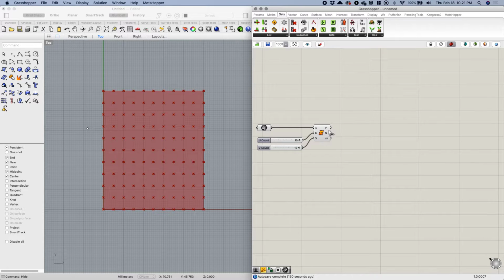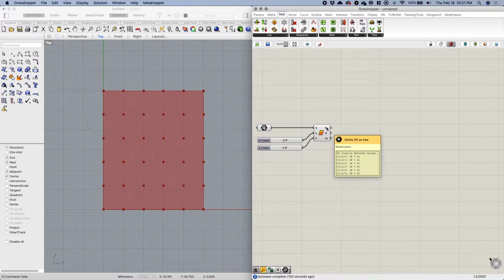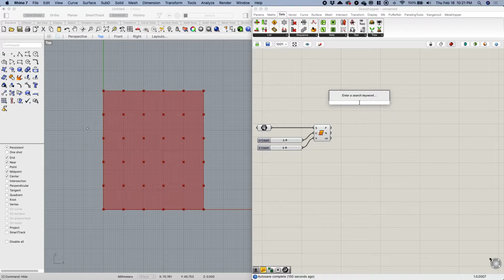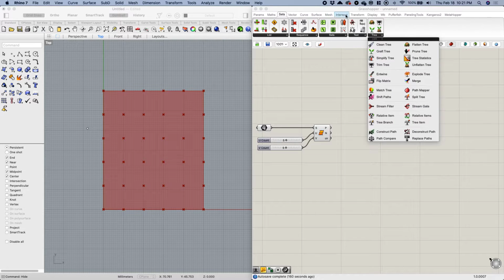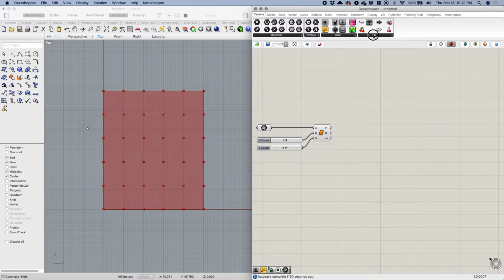And this is basically going to output a grid. And so it's similar to the rectangle grid component in that I get a tree structure, and this has 11 branches, each with 11 values in it currently because of my sliders here. If I bring these down, I'll have fewer branches and fewer elements per branch. And so to visualize that, I can go to my params util param viewer, and I can hook that up here, and I can see my data tree.